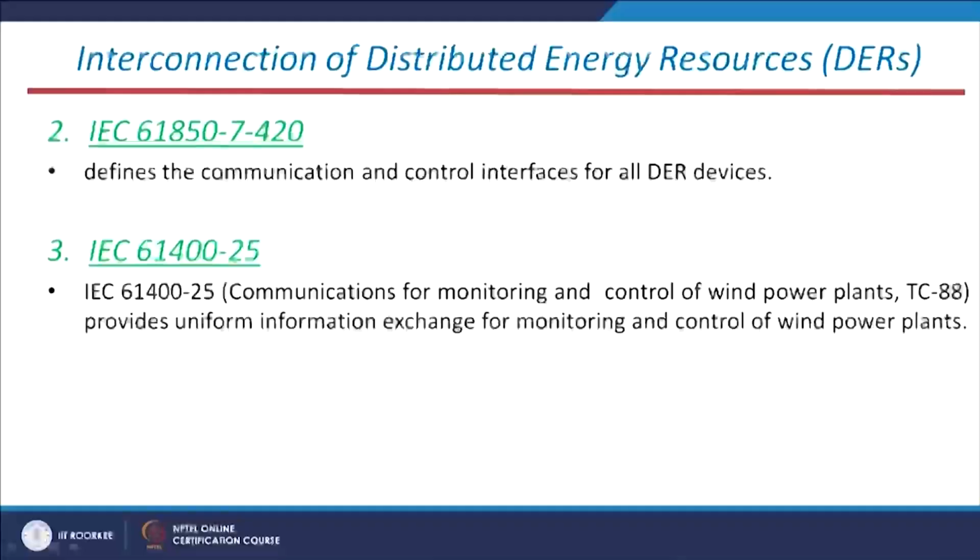Here I just want to discuss IEC 61850-7-420. It defines the communication and control interface for all the DER devices. It is basically a communication protocol package, standards or rules on how to communicate and how to interface all the DER devices through the communication medium to the main grid. That is what is written in this IEC 61850 module.